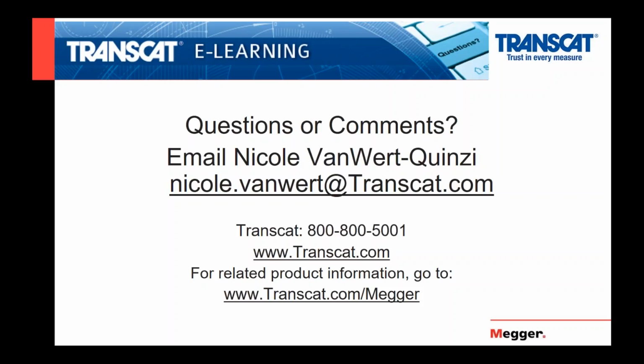We have already seen customers losing microwaves and refrigerators every 15 months or so. So having an analyzer capable of recording transients down to 1 microsecond, like the MPQ 1000 that I mentioned a few minutes ago, will help you identify the problem so you can take corrective action, saving you the time and money of buying and installing new equipment from transients taking out your equipment.